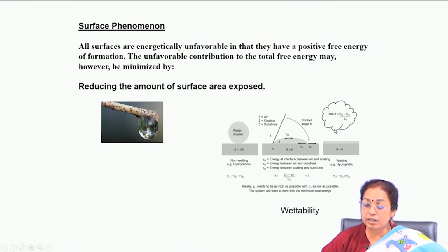So, a wettable surface has certain advantages, especially when you talk about materials for bioimplant application, it should be highly wettable. When you talk about a self cleaning surface, it has to be wettable. On the other hand, when you talk about a high corrosion resistance coating or a material which has to be applied in a water environment, with very high resistance to corrosion or erosion, it should be hydrophobic in nature. So, each and every phenomenon is driven by the surface energy.